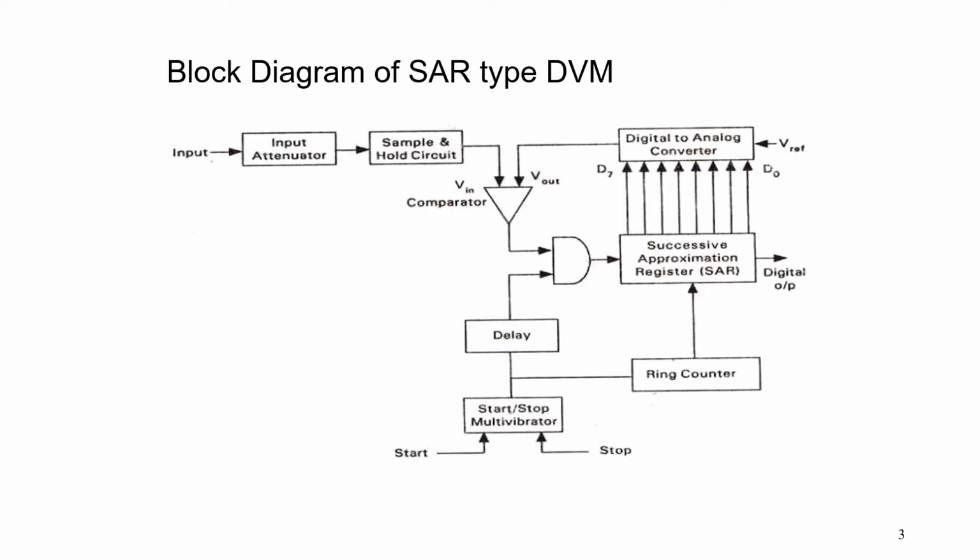In general, digital instruments have superior accuracy to analog pointer instruments, and many incorporate automatic polarity and range indication, which reduces operator training, the measurement error, and possible instrument damage through overload.